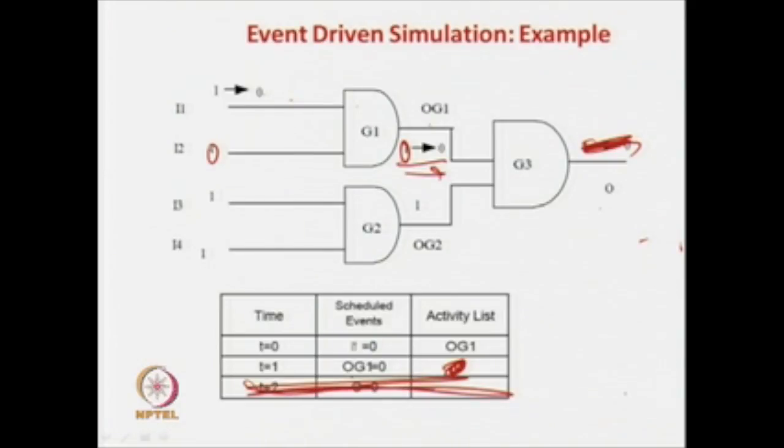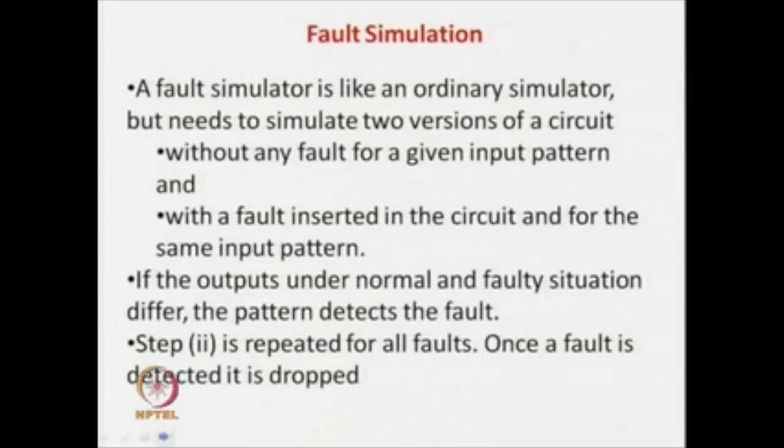But if you are using compiled code simulation, then you have to evaluate this, evaluate this, evaluate this and so forth, and it is a waste of computation time. So event driven simulation is helping a lot.